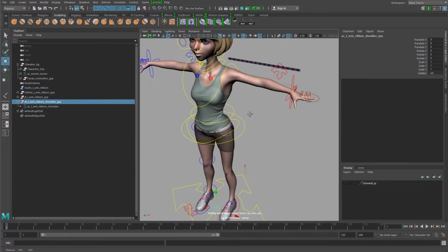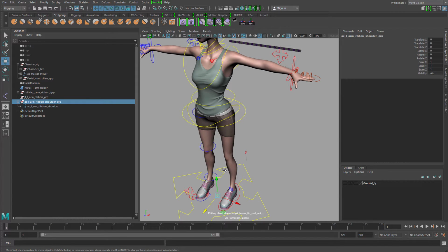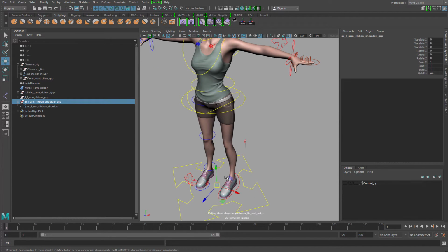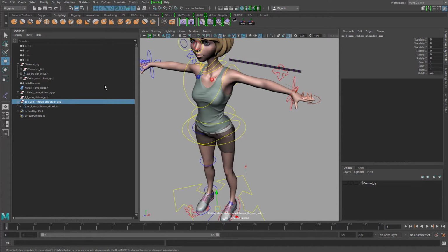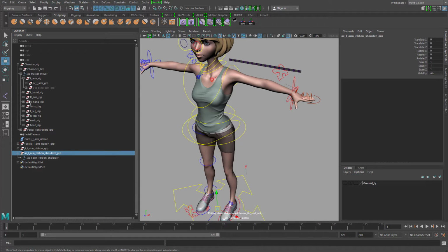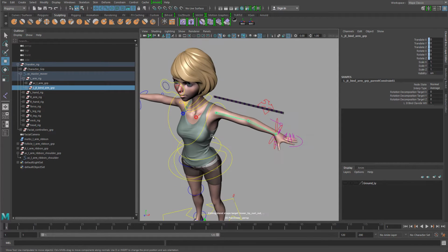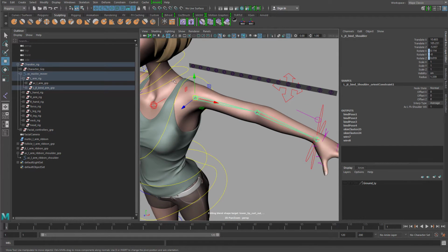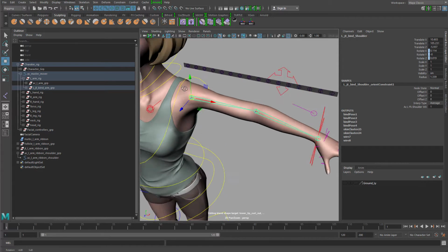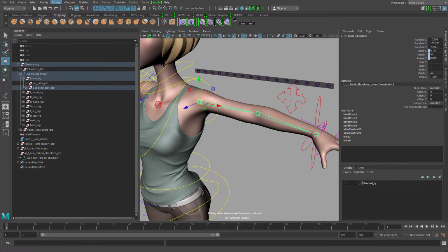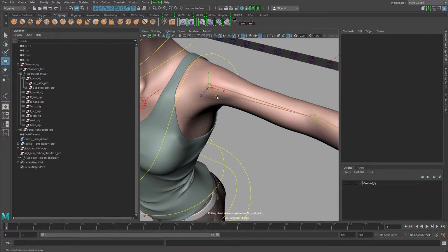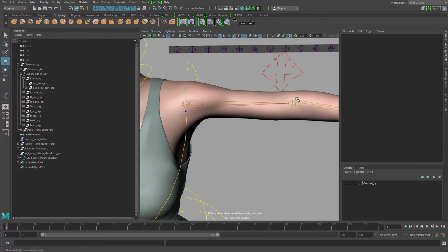Now one thing you want to make sure this joint has is that its X, Y, and Z direction is pretty much aligned with the shoulder joints. What I mean by that is if you go show the shoulder joints, and let's select it and go display, transform display, local rotation axis, you will see its axis going downwards or lower hierarchy.